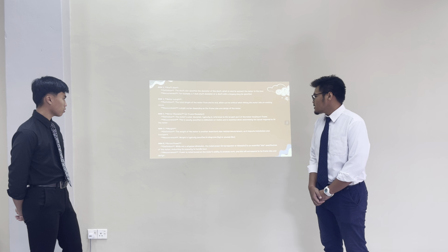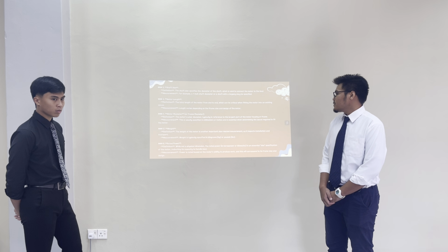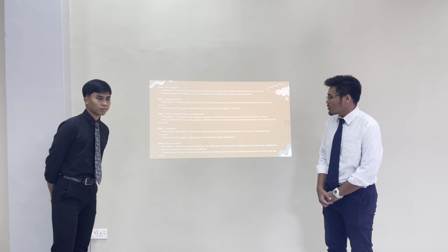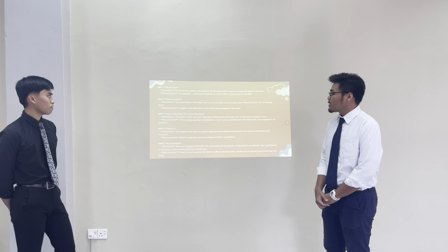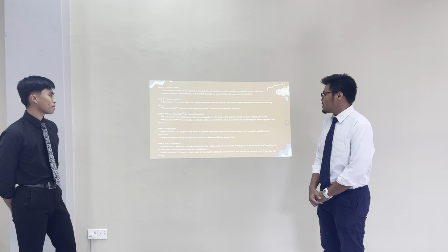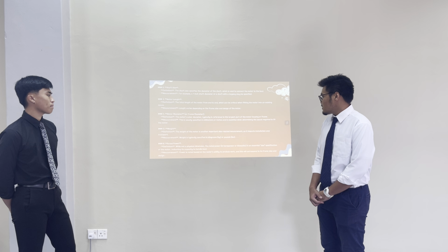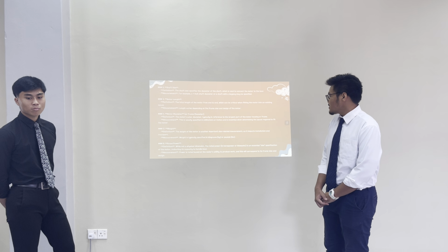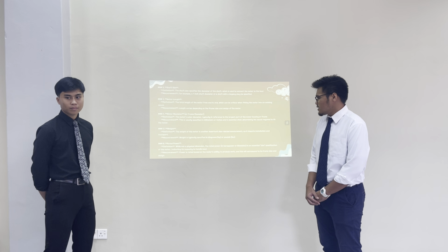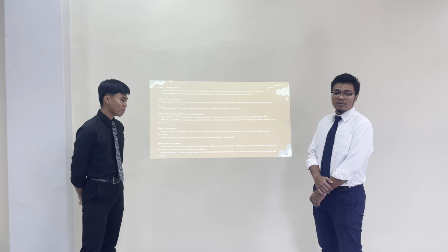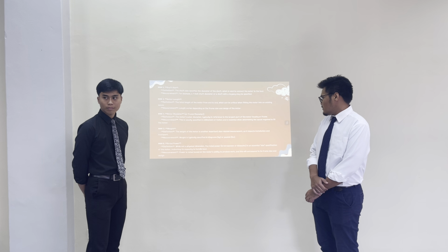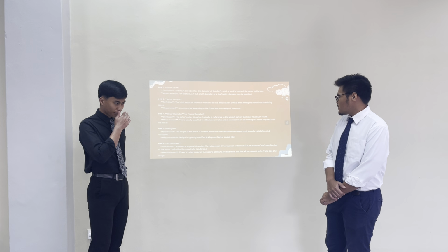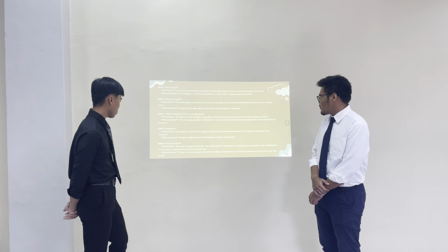Measurement: length varies depending on the frame size and design of the motor. Number 4, motor diameter or frame diameter. Definition: the motor's outer diameter, typically the reference to the largest part of the AC motor housing or frame. Measurement: this is usually specified in millimeters or inches and is essential when determining the space required to fit the motor.